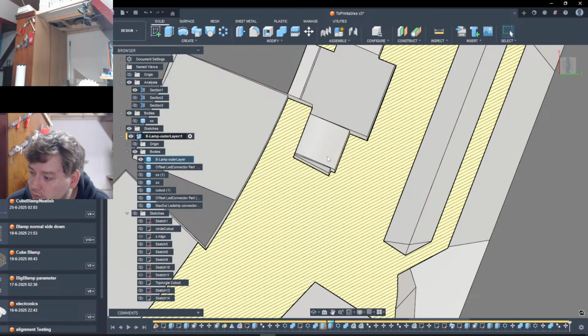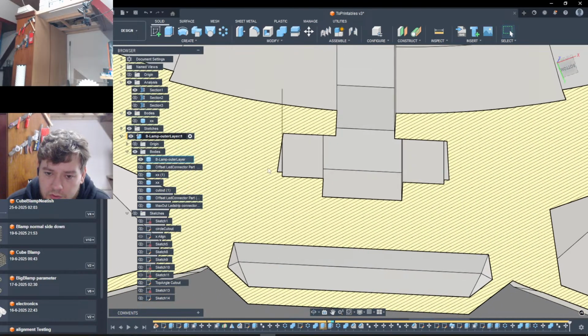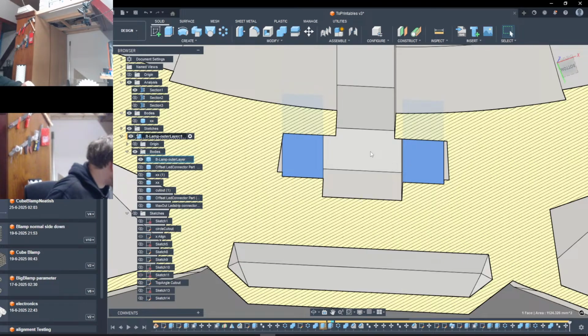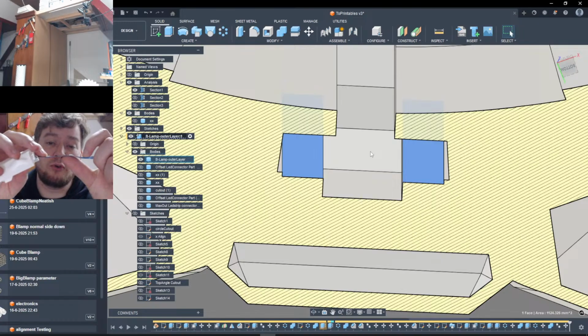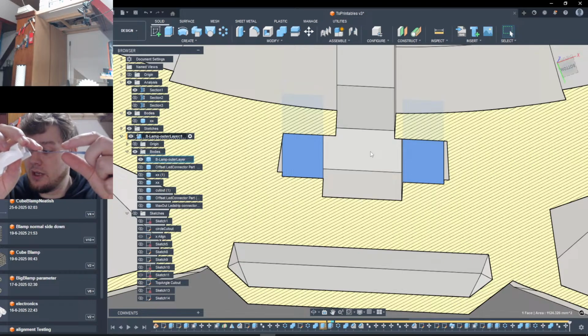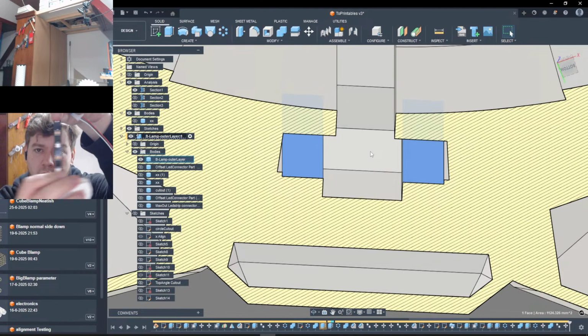How do you set the position of the strip connector such that the LED strips are centered in the middle of the hexagon? Well, I have no play on this side to this side, so this is half a millimeter bigger than the LED strip itself, so there's no way that it can go left and right. Up and down is measured out, because I know that the LED strip to LED strip is literally 33 millimeters from one to one. That's how I know the height, and left and right there's no wiggle room.